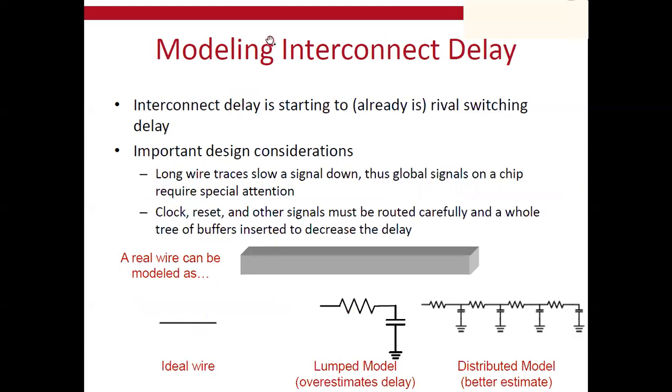And here is a very important parameter considering the effect of the interconnection in adding delay, not only resistance. Another important factor here is this lumped model, equivalent to a resistance and a capacitor seen by the interconnection between gates.